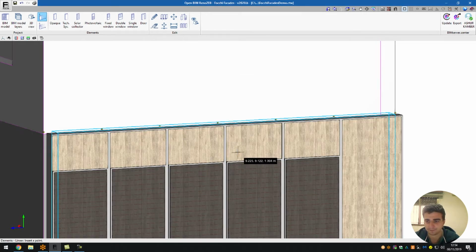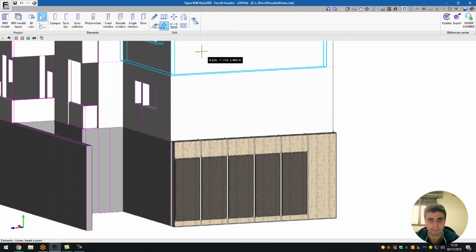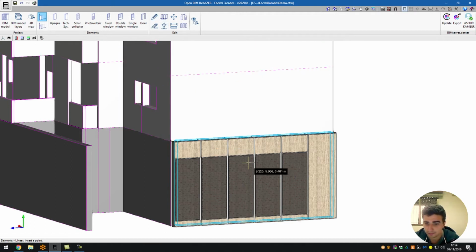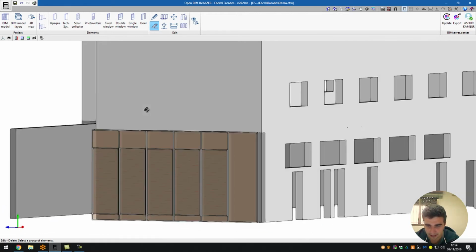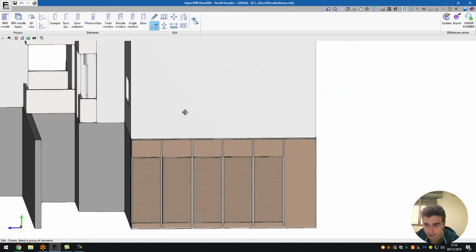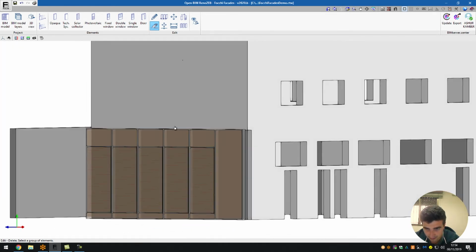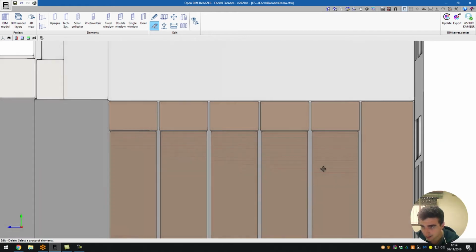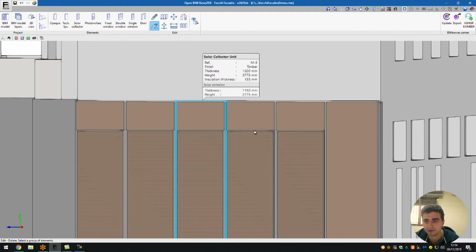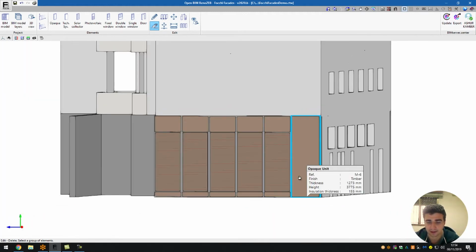Let's accept those changes. As you can see now, those changes have been inputted, and you can see my solar collectors here, but we do have one problem: this last solar collector here. What's happening is the program has decided that a solar collector cannot exist on the edge here. That might be because the wall isn't thick enough for two of them, but that can be overridden quite easily. Let's go to our delete option.